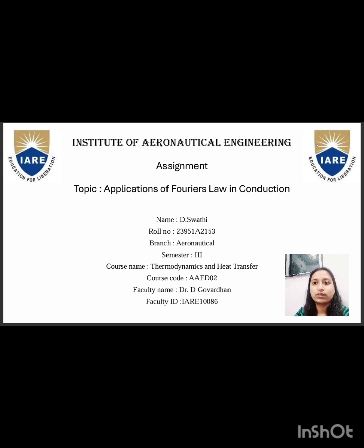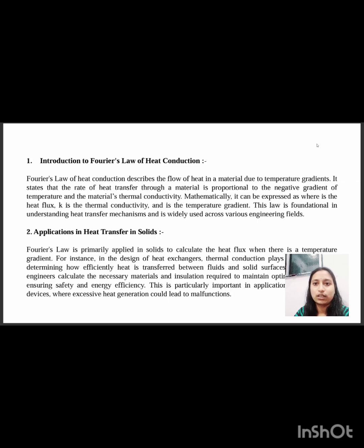First, we have the Introduction to Fourier's Law of Heat Conduction. Fourier's law of heat conduction describes the flow of heat in a material due to a temperature gradient. It states that the rate of heat transfer through a material is proportional to the negative gradient of temperature and the material's thermal conductivity. Mathematically, it can be expressed as q = -k dT/dx, where q is the heat flux, k is the thermal conductivity, and dT/dx is the temperature gradient.